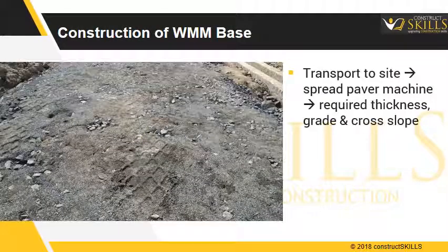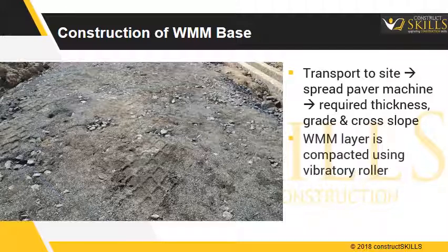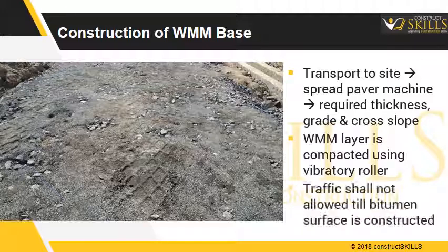The WMM mix is transported to the site and is spread using a self-propelled paver finisher machine, to the required thickness, grade and cross slope. The WMM layer is compacted using a vibratory roller. No traffic shall be allowed before a bituminous surface course is constructed.